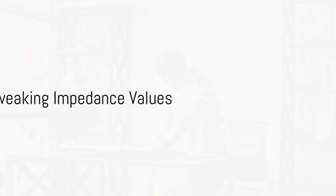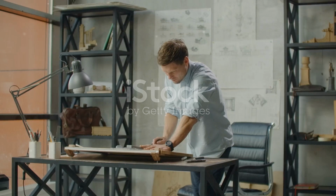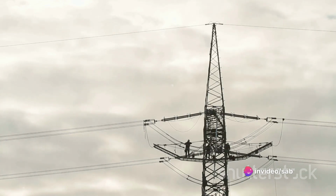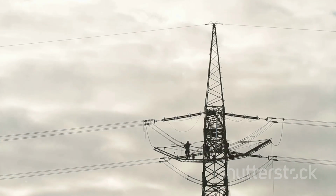With the Smith chart at their disposal, engineers can nimbly analyze and tweak impedance values to match a desired load impedance with a source impedance. It also serves to design impedance matching networks, such as transmission lines, stubs, or quarter wavelength transformers.